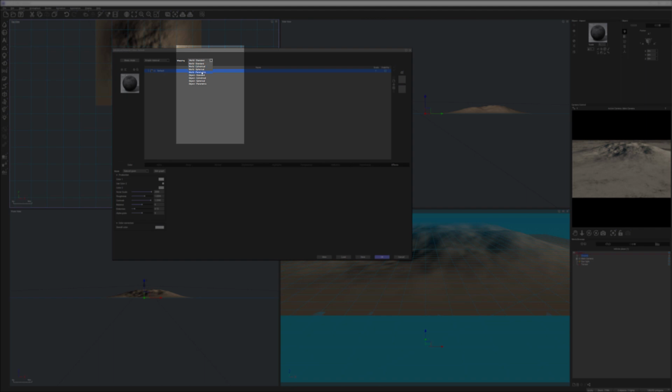Parametric is very important, because in this mode the coordinates automatically adjust so that they are independent of the size of the object, and the mapping is fitted to the size of the object. It's important when we start using something like a height field displacement, or some other mapping that we may produce in another application and import. We'll look at this in a second. The same applies to object: the world option will use world coordinates, mapping to the whole world, the ground, while object will be on the object specifically.